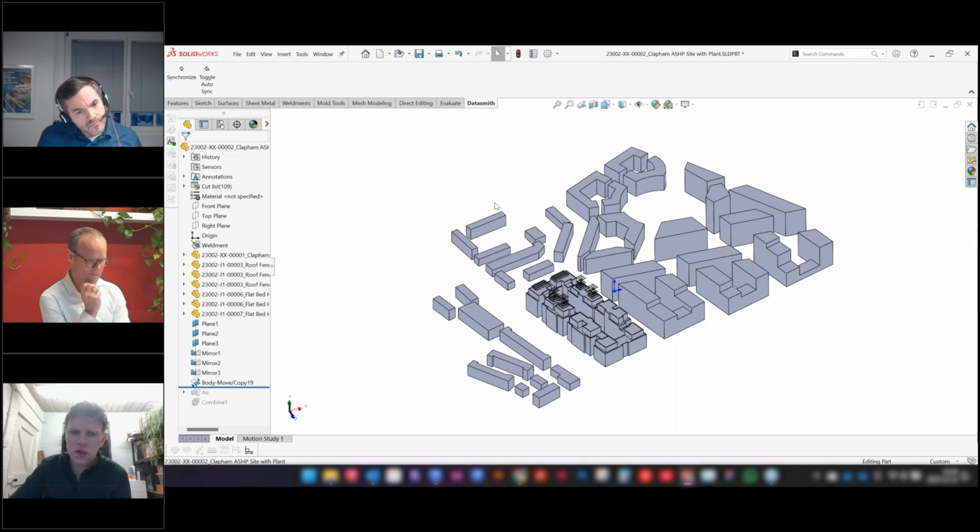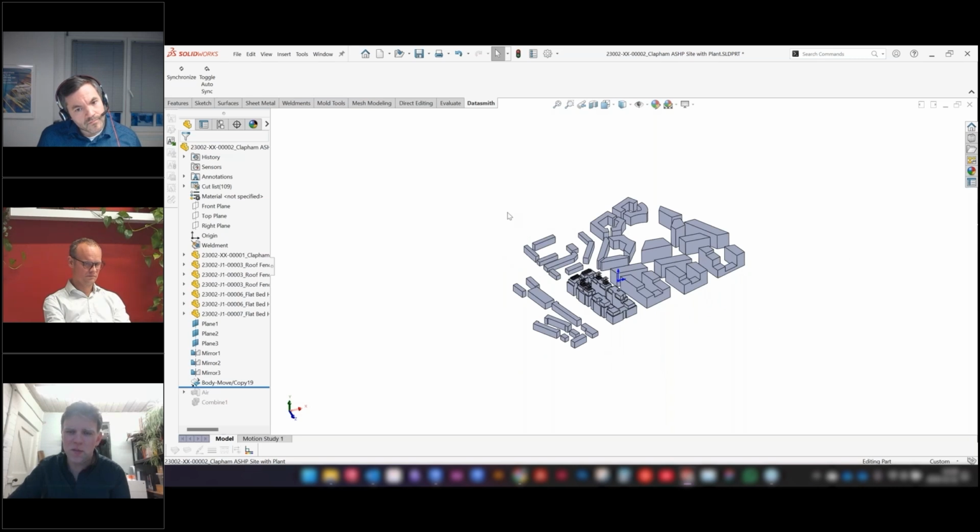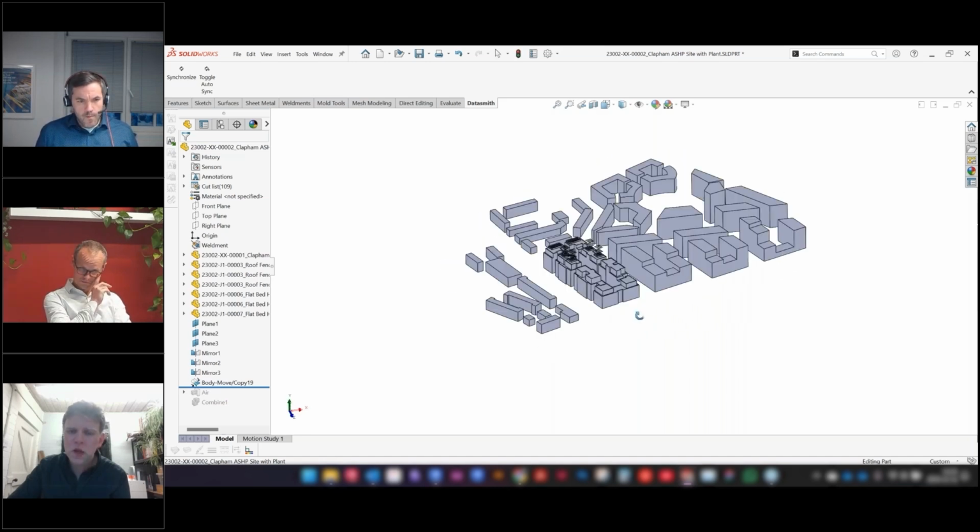The scale at which we actually model. So this is a selection of buildings, not obviously all the buildings, because there's a lot more buildings in the built environment around here. But what we don't model is everything. So we're not interested in trees because of the transparency when it comes to the air and their complication when it comes to the CFD. We don't have roads. We don't have every single building. We're interested in buildings that might be sheltering the heat exchangers, which is what we have here.